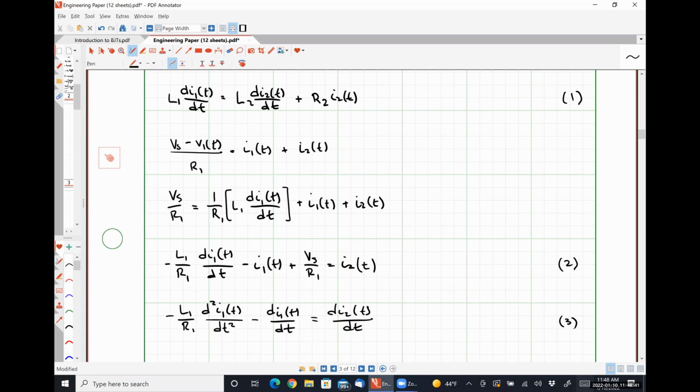You just then have to think of, okay, well, how do I relate those mesh currents to the inductor currents, right? Because a mesh current represents a current flowing around a loop, not so much a current flowing through a particular circuit element. Similarly, if you were going to do nodal analysis, you'd need to figure out how to represent your nodal voltages with capacitor voltages, right? Or I guess technically, you could represent them with inductor voltages and then thereby inductor currents and so forth. All right, so do we need to go through the algebra of combining all of this junk again?